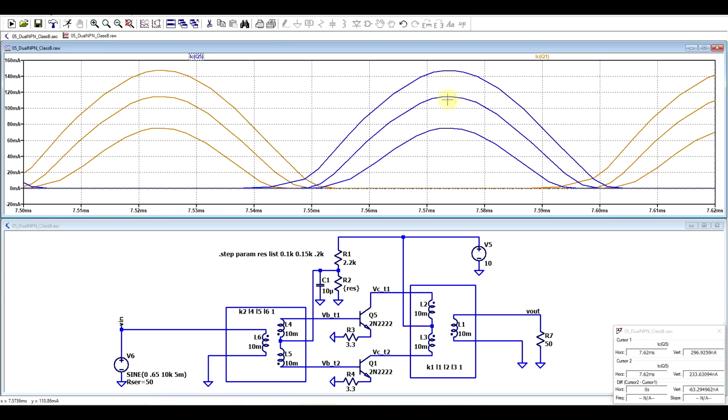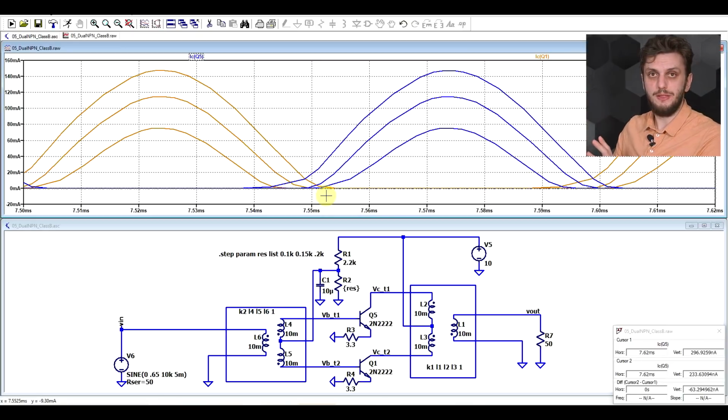The second lines almost touch, so these are almost exactly 180 degrees of conduction angle, proper class B operation, which is providing distortion. And then the last currents have a clear overlapping region. So this is what class AB looks like. So constructively, they're all the same thing. It's just that the bias point is set slightly higher or lower.